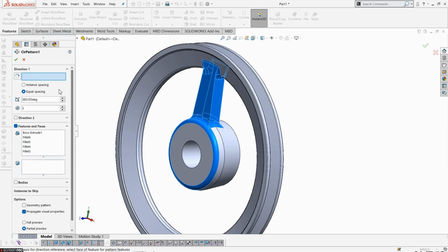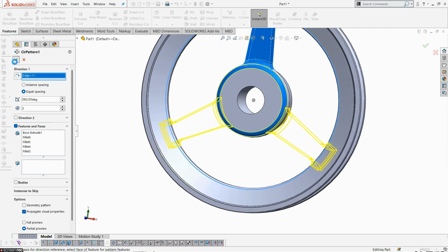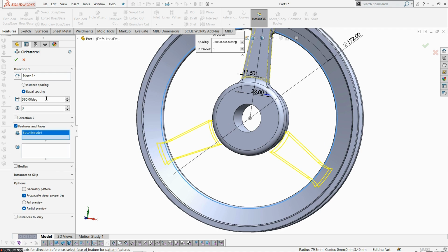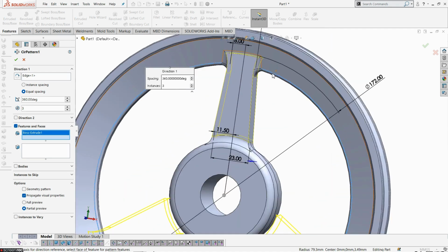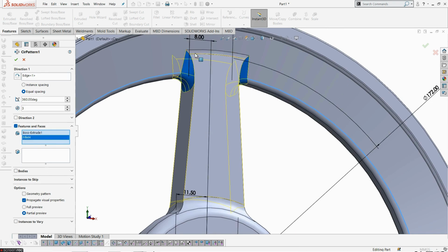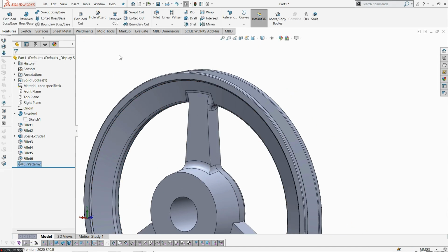This time I just select 4 different fillet edges. Let's make it a solid formation by using a pattern in 3 different areas at 120 degree. In this condition it is not formed within each other, that's why I remove one of its radius. Clear the selections and only select the solid formations, and choose this 4 mm fillet radius. Form this fillet formation equally by selecting it at 120 degree. Okay, now it is equally split.